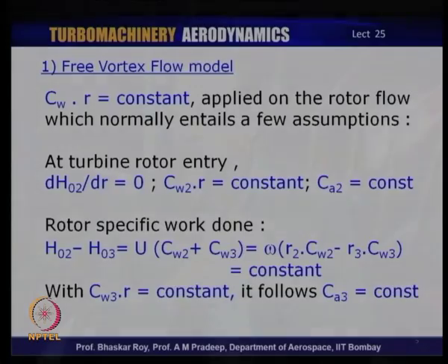Now, that variation of degree of reaction may have certain issues. Degree of reaction in a turbine can vary from near 0 to very high degree of reaction, which could be 0.5, 0.6, not as high as you get normally in axial flow compressors at the tip, but quite high. And the mean or the mid radius degree of reaction for turbines is somewhat less than that of axial flow compressor. So, typically that symmetrical blading that we have done in case of axial flow compressor is normally not done at the mean radius of turbine design.